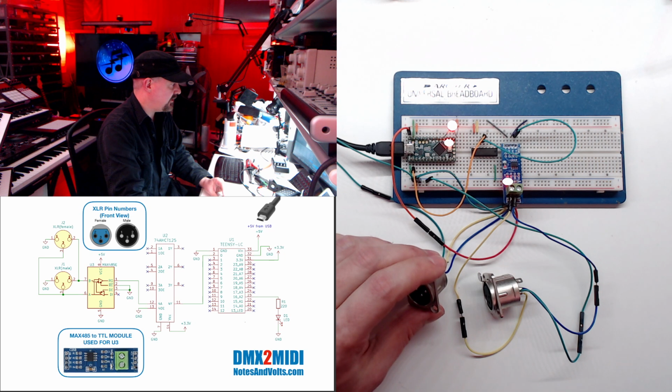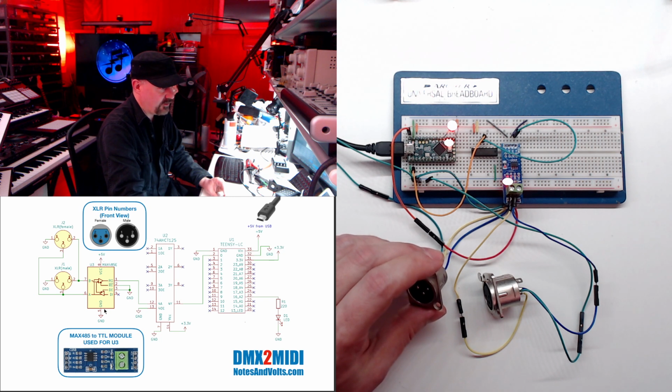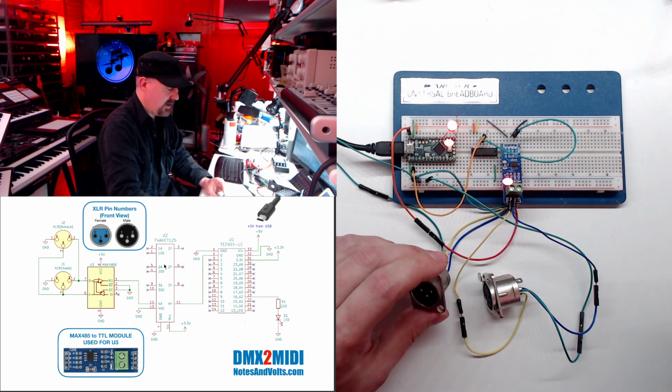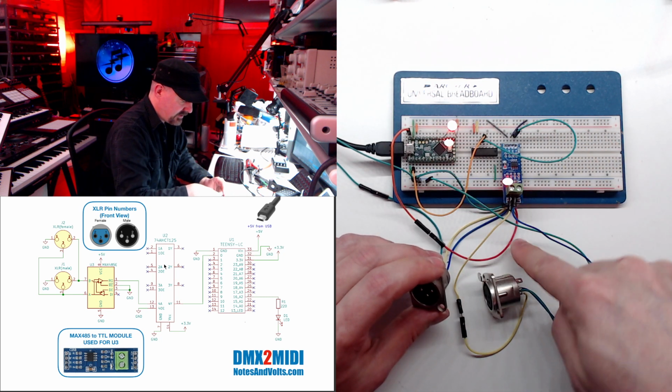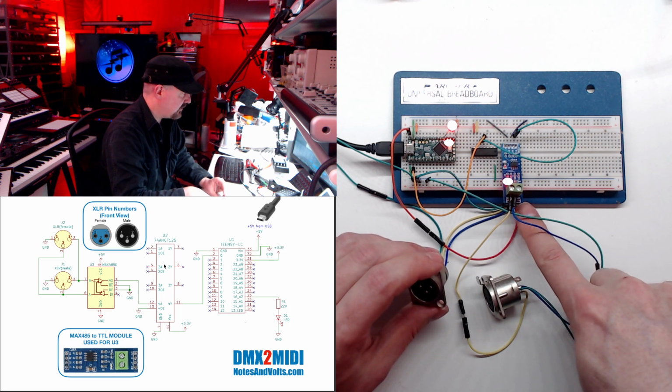So if you take a look at the input section here, there are 4 pins. There's a VCC, a B, and an A, and a ground. Now, first of all, we need to provide power to this chip. So you can see our VCC is 5 volts and our ground is ground. So to get our 5 volts, we're going to take it right from the Teensy's 5 volt pin. And you can see I've run a wire from that pin all the way under here and into this pin